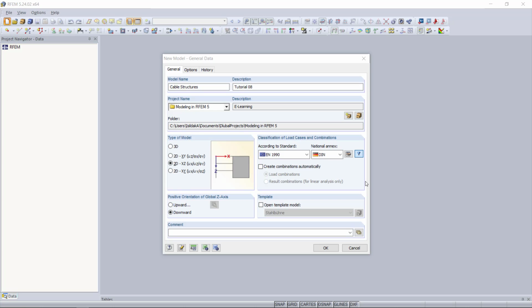So if you have, for example, bracings, it's better to choose tension as member type instead of a cable. Apart from that, we also have the add-on module RF-FORM-FINDING, and with that we can set, for example, the cable absolute sag, which we will do for our example later. So much for some theoretical aspects, and now we will start modeling our structure.